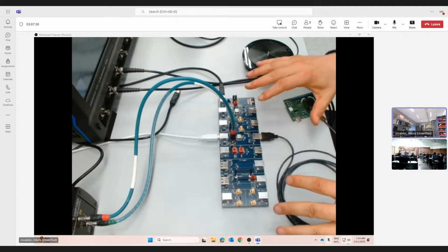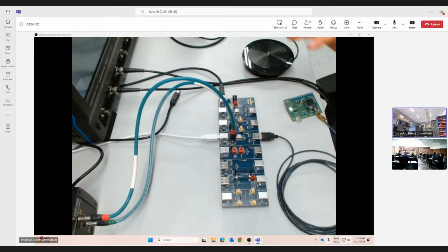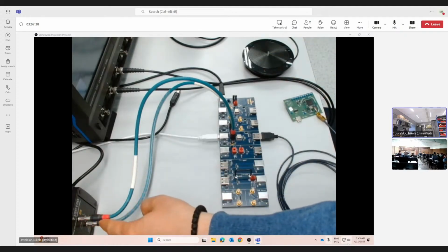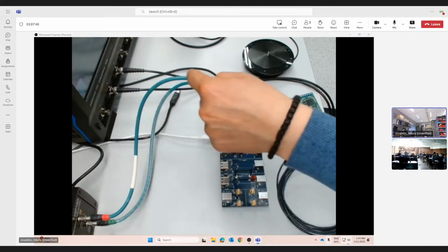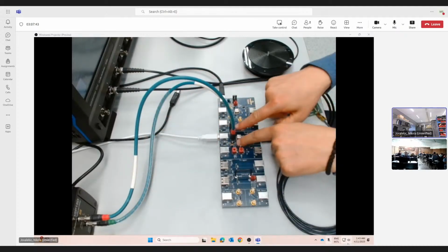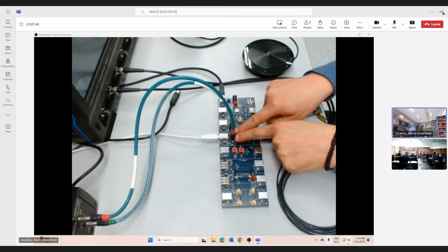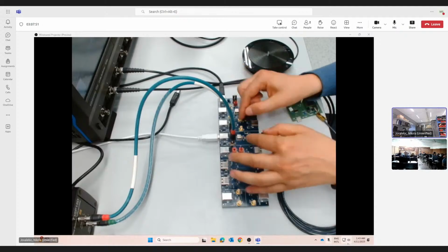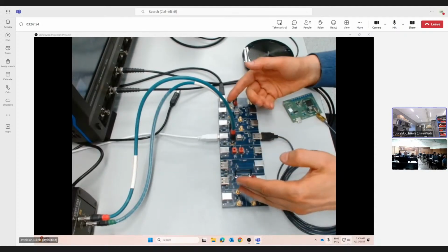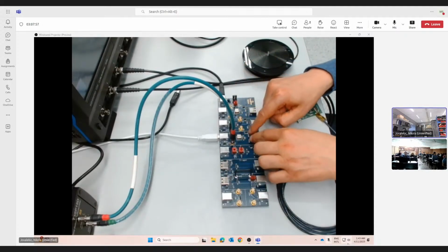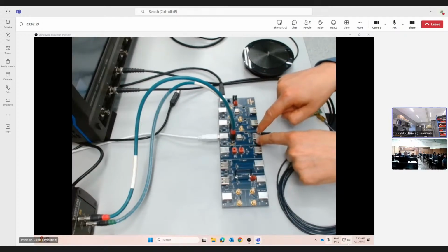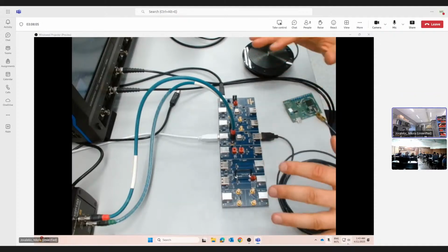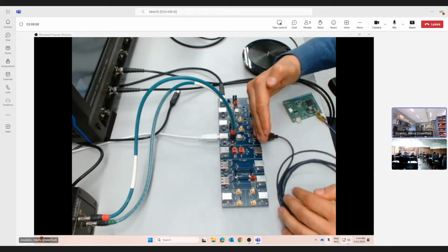What will happen in this setup? Just simplified. I will not bother you with the details. So signal is coming outside the TDR to these cables. It will encounter here on these connectors some reflections, of course, because we changed the geometry and we changed the impedance. It goes here on the traces on the PCB, and then it comes to our cable. I will not bother you with the calibration and these things.